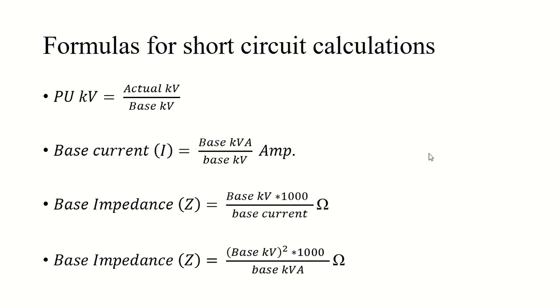If you have seen the numericals related to transformers, we do it a lot. In order to find the value of current, we take the ratio of kVA to voltage. So we are doing the same: by taking the ratio of base kVA by base kV, we are finding base current here.